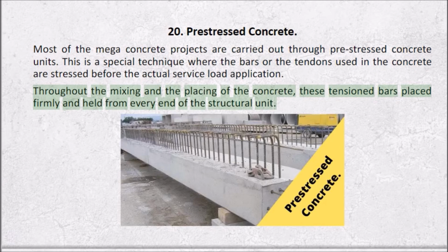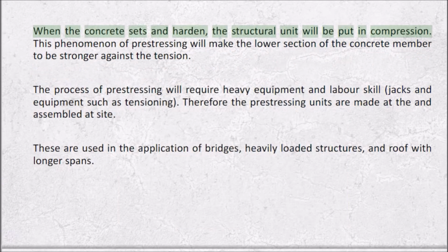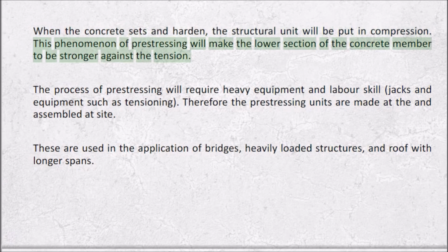Throughout the mixing and placing of the concrete, these tensioned bars are held firmly from every end of the structural unit. When the concrete sets and hardens, the structural unit will be put in compression. This pre-stressing makes the lower section of the concrete member stronger against tension.